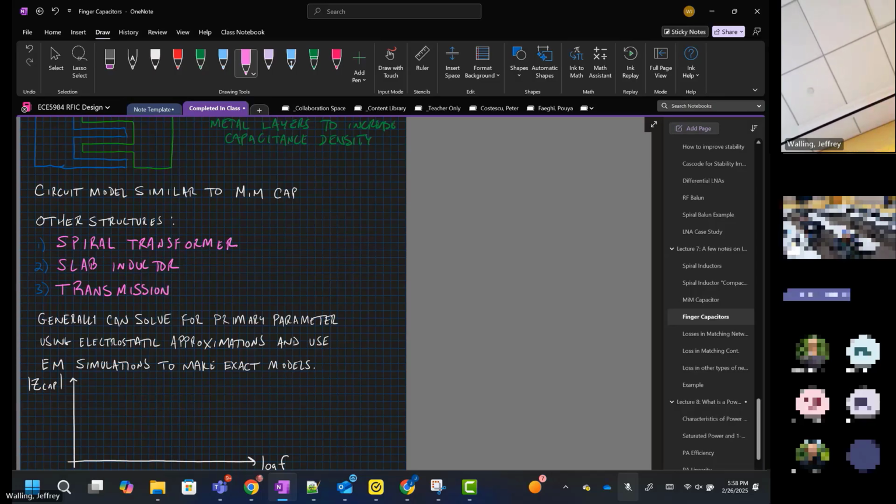Now, for the most part, when we're on chip, we tend to want to use lumped element components because transmission line based components are things where we're using some large fraction of a wavelength, so even up to relatively high frequencies, those components can be quite large on chip. So we favor using lumped components where possible. And generally it is possible. But we will see as we get towards 100 gigahertz, we'll start to see transmission line components.